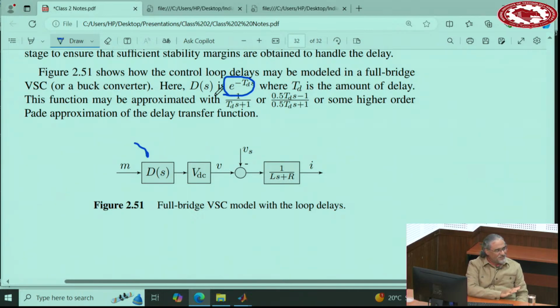So you pay a price. If you want to really speed up and bring the time constant of your system closer to the delays that your system has, you need to model the delay and bring it into your analysis and your control design. That's the price you need to pay. From a control perspective, you need to work with this system, which is not a very easy system.